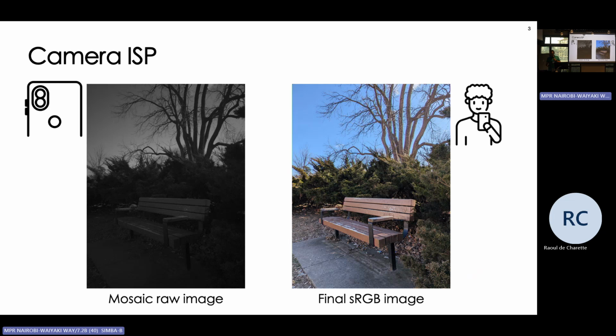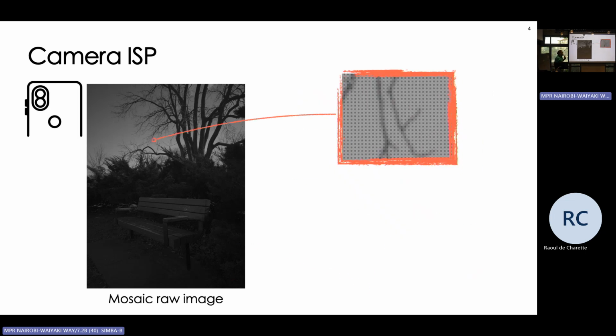So I just wanna confirm that you got it. When I open my camera here, for every single frame shown, there are a lot of processes I will discuss. There are no standard ways, but there is the general flow. And that happens for each frame, like 30 times per second, for example. So we start with what we call the mosaic raw image. And if we have a closer look at a small patch from this image, you can see this dot pattern in this image.